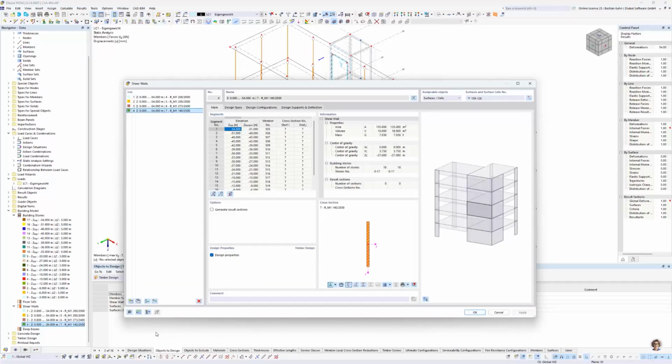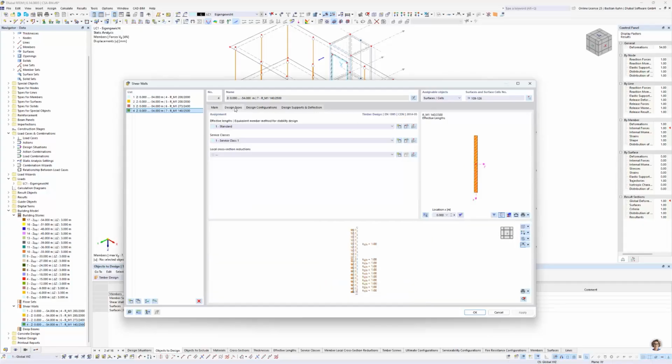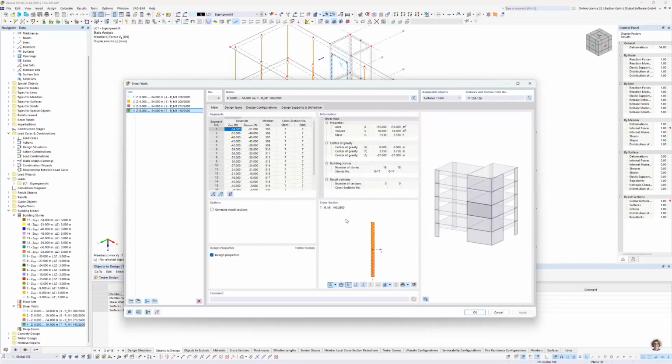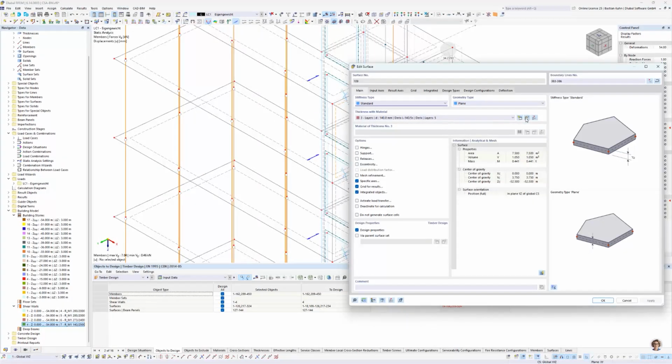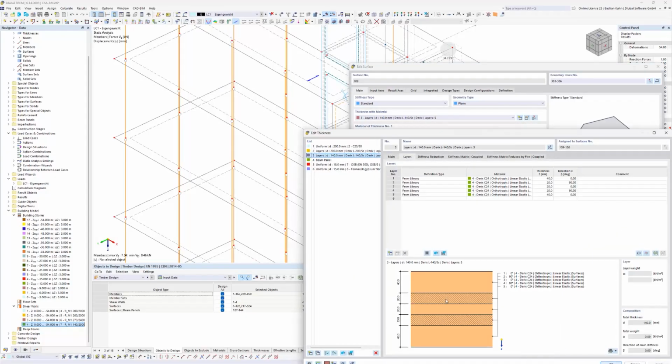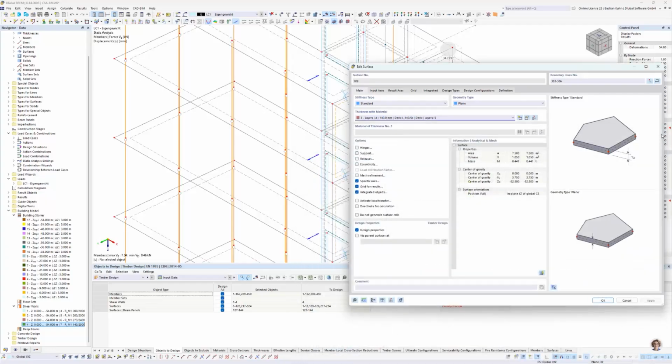You can say, okay, I have this here, and it's generating a result beam. And now, surprise, here you have effective lengths. But the problem is, this is now for a width of 14 centimeters. And when you take a detailed look, 14 centimeters is not really correct, because I have middle layers of at least 4 centimeters that I need to eliminate from the stiffness, because they are oriented in the other direction, and in vertical direction they have a very, very low stiffness, at least theoretically.